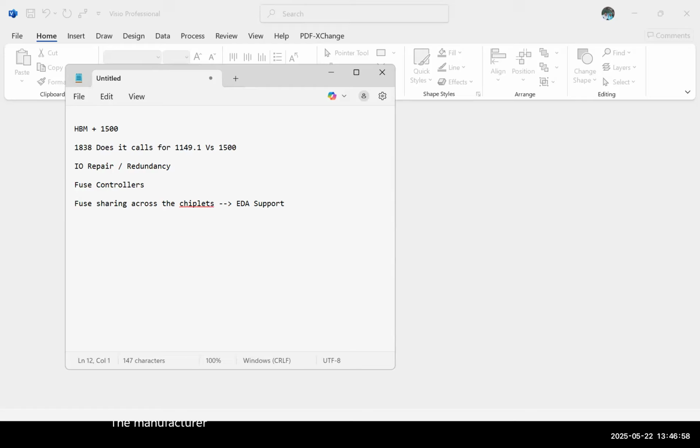For any repair kind of fuses, like memory redundancy, for example, you run the memory-based test in the wafer test, you find some bits are not operating, and then you have a chance to repair it. So those fuses are blown at the wafer test itself. In the final test, the hot temperature and low voltage kind of testing is done, because they distribute the wafer testing and the final testing with respect to different temperature, low voltage and high voltage selections based on plus or minus 3 sigma.